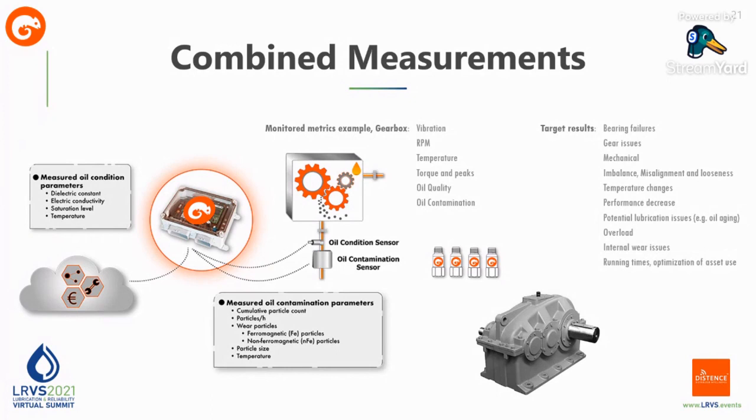Because the system is this versatile, the entire drivetrain can be monitored in the same system with the same accuracy. The electric motor is monitored and its bearing lubrication can be scheduled based on lubrication indicator. The gearbox is covered with vibration and oil analysis.